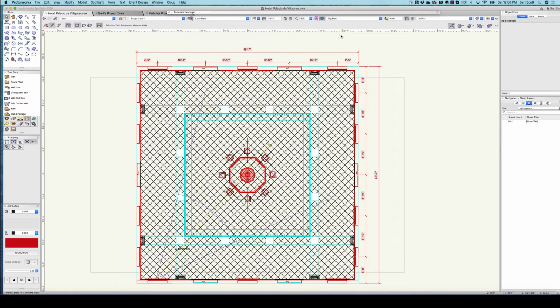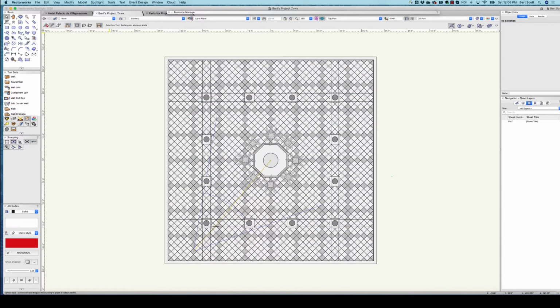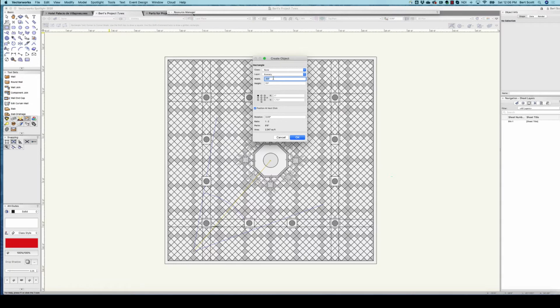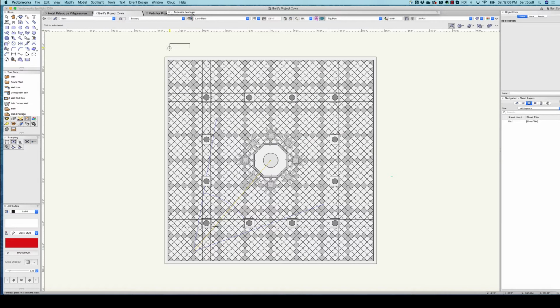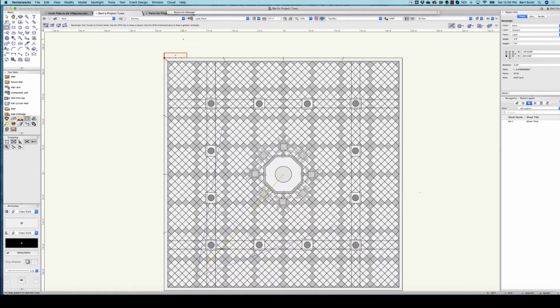Next, we'll put in the doors and the windows. So here's the layout for that. So what we're going to do is draw some rectangles for spacing, and then we can copy the doors and windows in from last week's file and insert them into the walls. So back to our project. So first we want to create a rectangle that is 4 feet 5 by, it doesn't matter, I'm just going to do 12. We're going to insert it by its lower left hand corner, and we're going to put that right there.